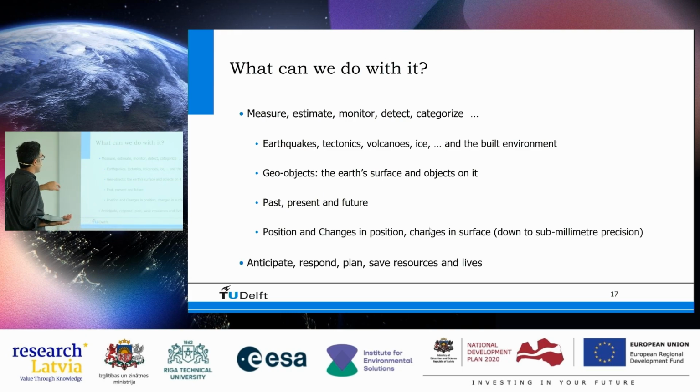And then finally, if I start with these verbs to see what we can do with it, the most important thing practically, going from the technique to real applications, is we can anticipate. We can think, okay, if the street moves with 3 millimeter per year relative to the building, then over 10 years, 3 centimeters, over 20 years, it's 6 centimeters, right? So we can anticipate for a pipe or for a bridge or for a railway that at some point in time, if that rate continues, things are gonna break, right?